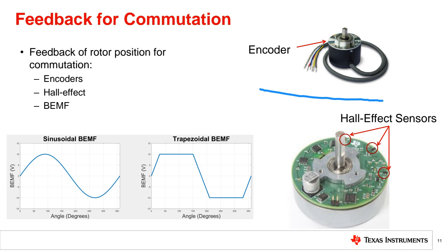Another issue is sensorless control. Sometimes we use sensorless control when you don't need a low speed range. Don't forget, we have two types of control: sensor and sensorless. The main disadvantage of sensorless is low speed region control.